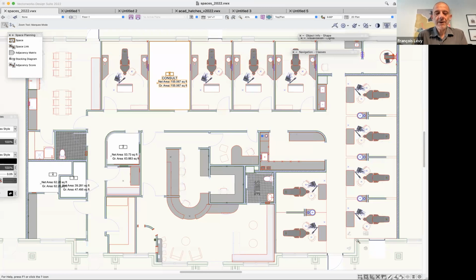Yeah, that would be the way to do it, because some Vectorworks objects are class aware. So, for example, if you try to fit walls to objects on another layer, but the class that you want to fit to is turned off, it won't. The wall won't see it. It'll see it if the layer is turned off, but it won't see it if the class is turned off. But the space object is going to see that baseboard whether the class is on or off. So that's a good point, that you could just build in an offset to the space object for greater accuracy.